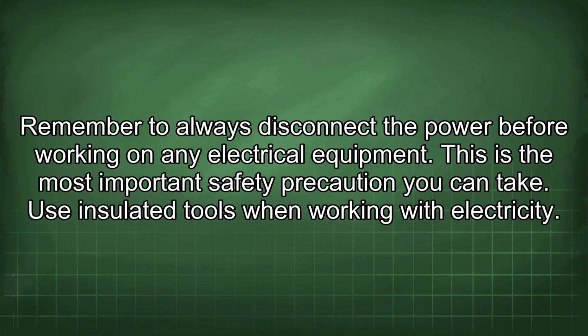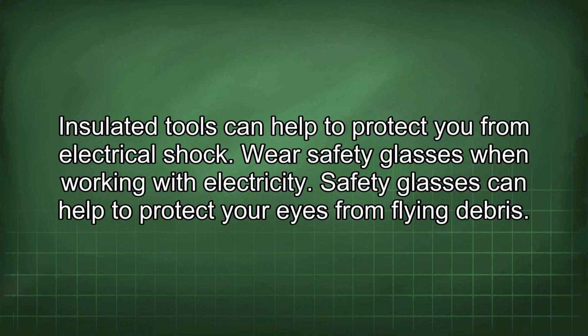Remember to always disconnect the power before working on any electrical equipment. This is the most important safety precaution you can take. Use insulated tools when working with electricity. Insulated tools can help to protect you from electrical shock.